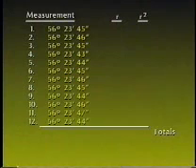Remember that systematic errors have magnitudes and algebraic signs that can be determined and therefore can be removed from the measurements. Mistakes or blunders must be detected and removed, and then the measurement should be made again. Let's look at a group of measurements and begin our study of random errors.